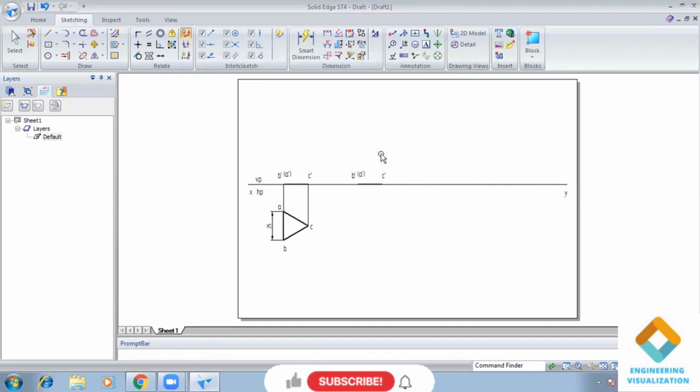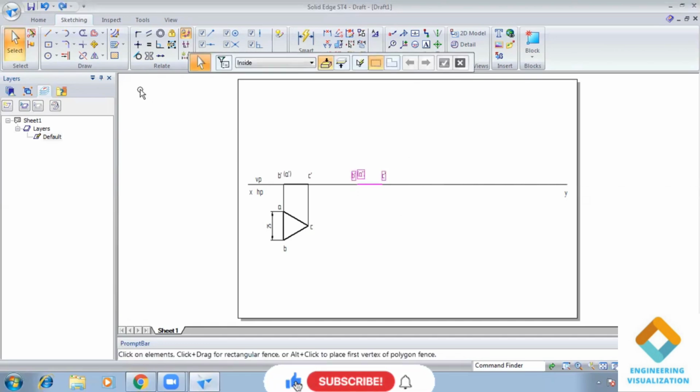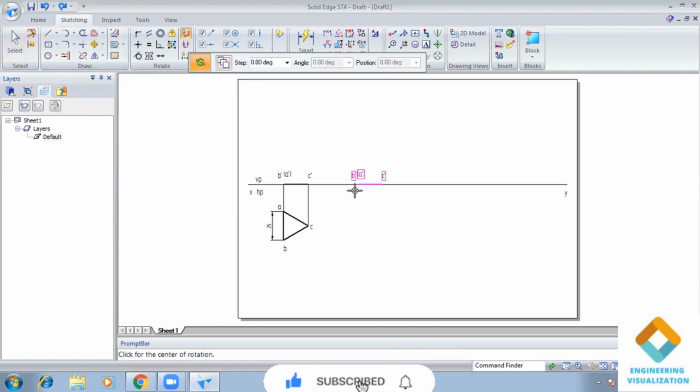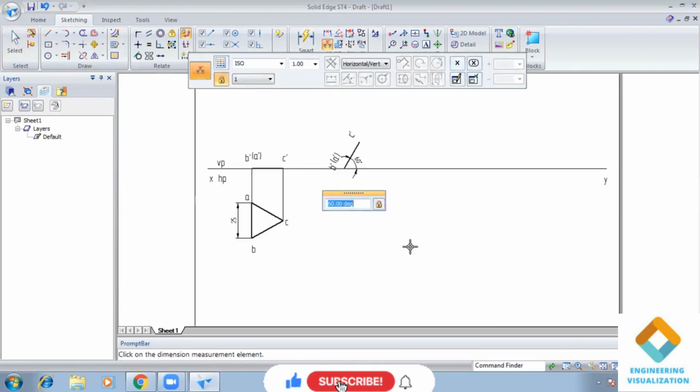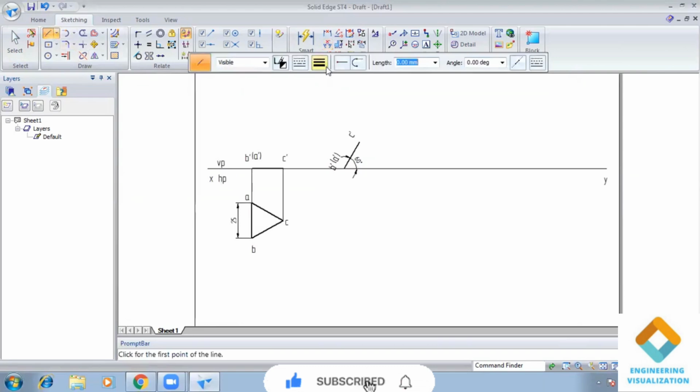Okay, unselect it, select the one end and the other end. Now rotate and give the angle 60 degree. Okay, now find out the angle using angle between command. Select the line and XY line, click on the fit, draw the projection lines downward.